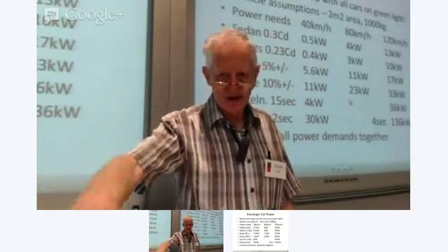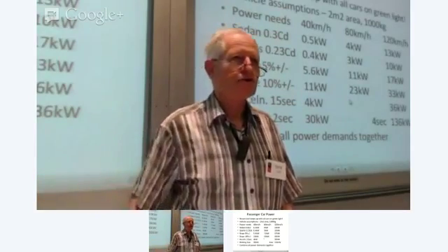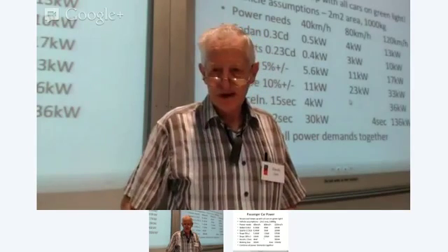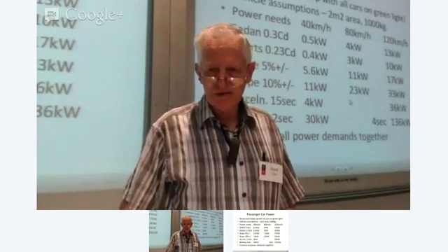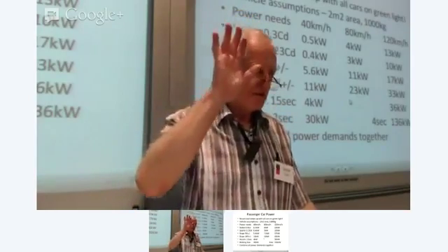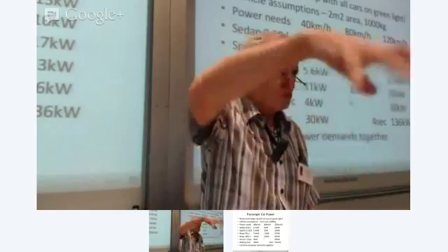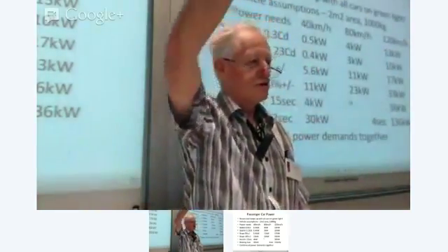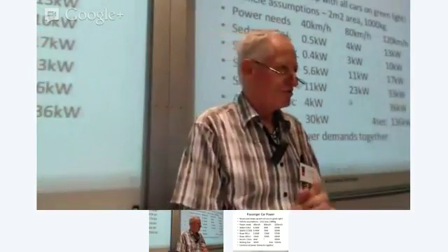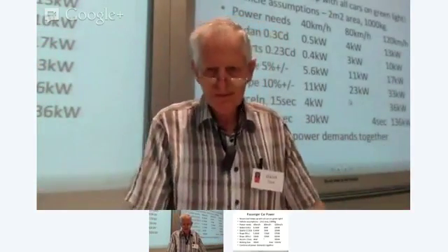For example, at 80 kilometres an hour, you need about 23 kilowatts to drive. Driving up there in Queensland, we had a Camry some years ago, and I remember at that 10% slope, fifth gear with full throttle would hold on the hill at about 80 kilometres an hour. So that 23 kilowatts provision was about right.